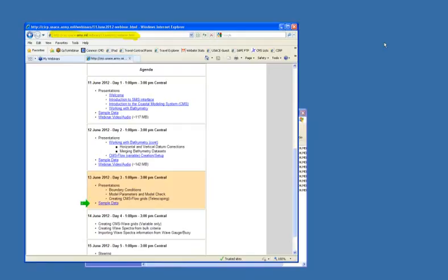Bear with me just a second. So we used refine points. 180 meters is the base cell size that we want in our grid, and we're using 1.08 here and 1.06 here, turning off the intergrowth between the points, and then we can click OK.